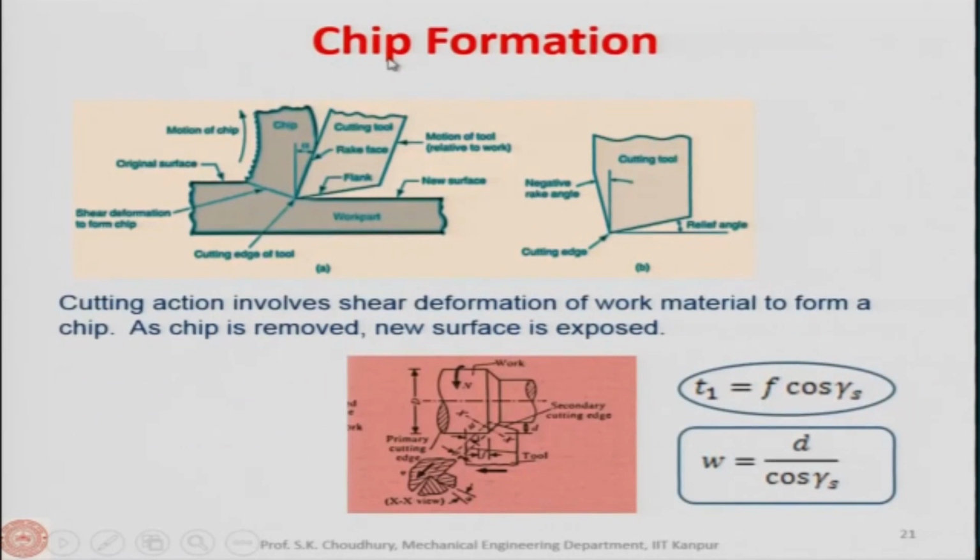Okay. Chip formation, in the case of chip formation, we said that this is the plastic deformation, and finally, it is the fracture. I have shown it to you in the stress strain curve or the load elongation curve, that after the point of instability, it goes in a triaxial manner and it fractures. Fractures means that it actually segregates. So, that is the chip formation, we are getting the chip. I once again repeat that.